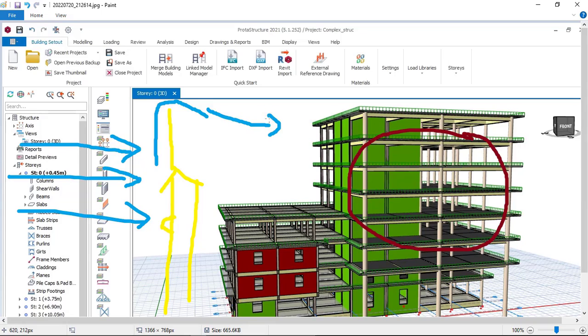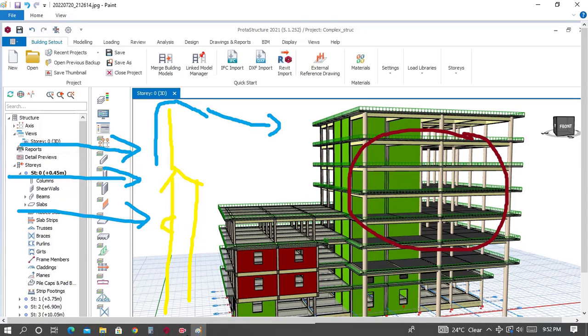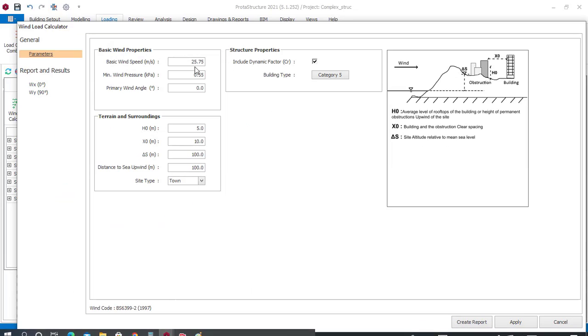So with that right now, that wind speed of 25.75 meters per second, as you can see here, which was coming to hit your structure, has now reduced because the wind found some obstructions like trees and other tall buildings around your building area. So the wind first hit that obstacle, then had to divert into your own structure, which will give less effect to your structure.